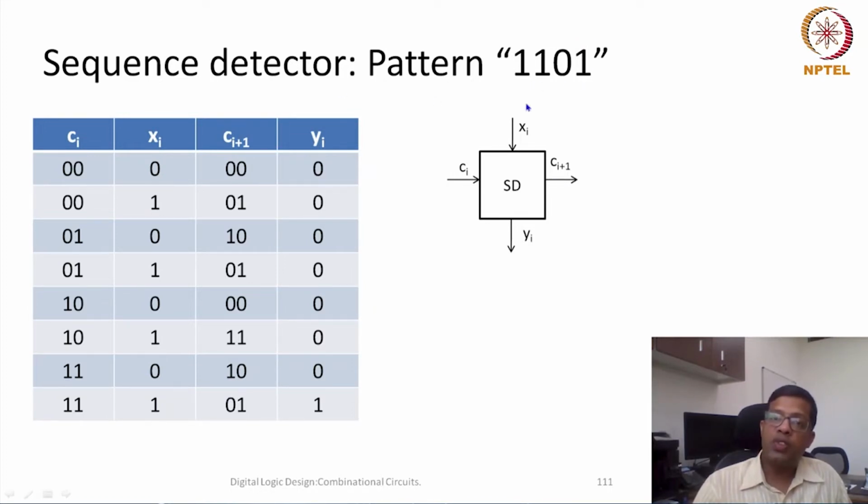So in a long sequence, we can say that only one input has matched in the pattern, so 0 1 would be the output here for Ci plus 1. In this way we have to see carefully for each and every input pattern, where we have formed, what we have created so far, and whether that particular pattern has matched how many bits of the current pattern. Okay, so once we have this truth table, now we know what to do.